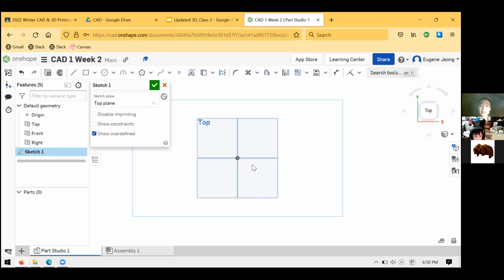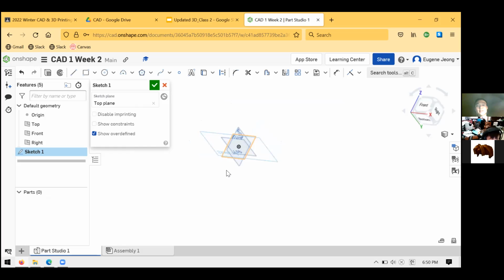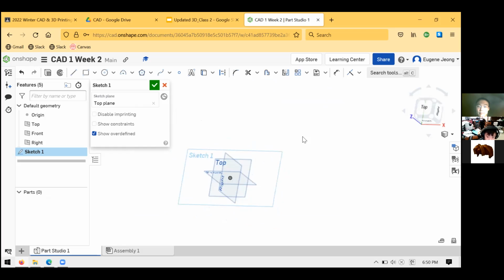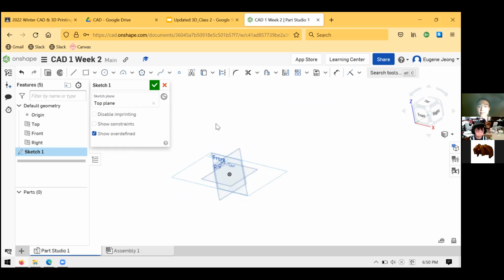Yeah, right now you're totally fine. So what's happening now is that the sketch is there. It's just that you aren't looking at it head on. So you can see there's this fainter, larger rectangle, and in the corner it says Sketch 1, right? And so that is your sketch. You also have the option to look at it from an angle, from a three-quarter perspective, or even from the side where you can't really see anything.